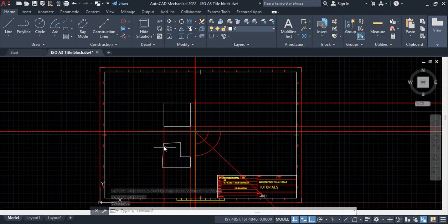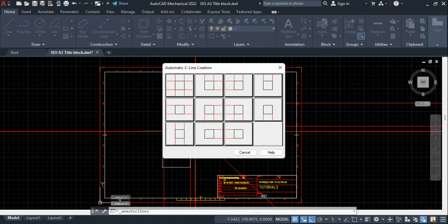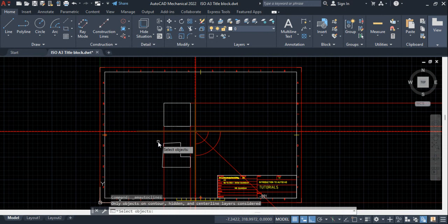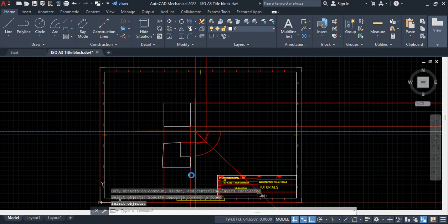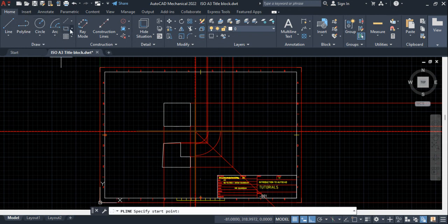Then I want to get this one too. So the same thing, I go here, all right, select, and then I choose this, only the one that is going to the east. So I select this one. Then I come and draw a box around my shape, press enter. Then it automatically generated. From here, I can get my side view shape.